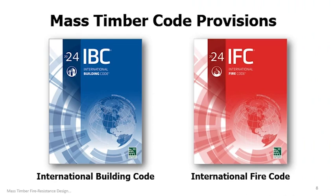I'll get us started with a high-level overview of the fire safety related building code provisions that are applicable to mass timber construction. Many of these code provisions rely on AWC standards like the NDS and the FDS, and design guidance in TR10 as well, Technical Report 10. I'll talk more about the AWC standards in the next portion of our discussion, but the code provisions that I'm mentioning here are from the 2024 I-codes. They're also the same as the 2021 I-codes, at least the provisions that I'll be discussing here. The I-code family includes the 2024 International Building Code and the 2024 International Fire Code, which contain the provisions applicable to these new mass timber construction types.